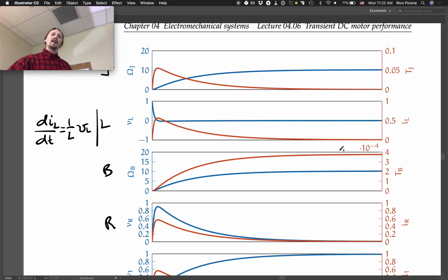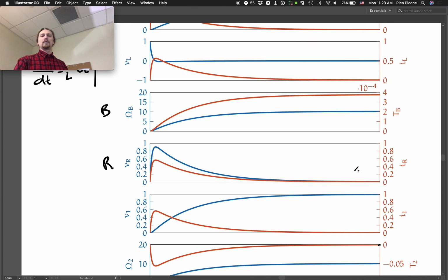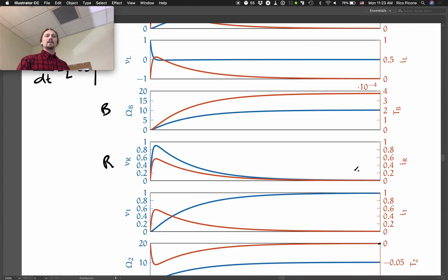But notice that at high velocity, or not really high velocity, but once we get up to speed, we're going to have a torque that is always impeding the motion, right? It's the bearing damping. It's never what you want. It's releasing heat. So, but we always have to deal with it. At low speed, it's not really in play, but when you get to higher speed, you end up with some torque that is impeding the flywheel.